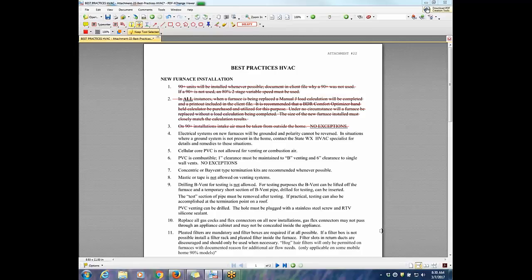All the manufacturers, if you're following the manufacturer's instructions, you properly ground the equipment. That's because of flame sensing or flame rectification. The equipment's got to have a good ground. I haven't seen any problems with this for years in our program.